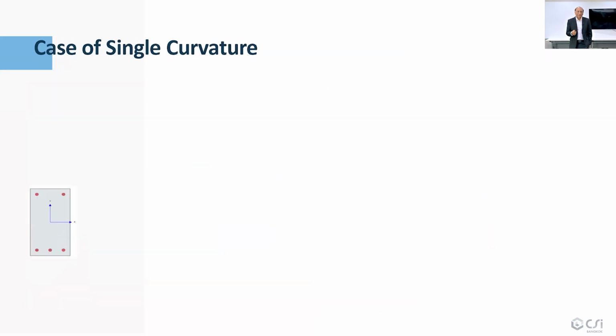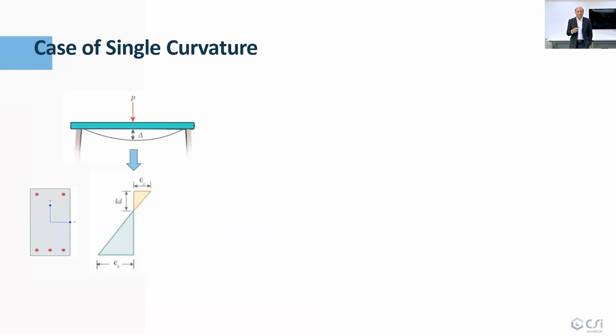We can repeat the same thing for a beam under curvature. Let's say it is under bending and then it has curvature. So it basically has a non-uniform strain and we have a curvature. In this one, same thing, the curvature will produce concrete stresses in some portion and zero stresses on the other, or small negative tensile stresses, and stresses in steel.